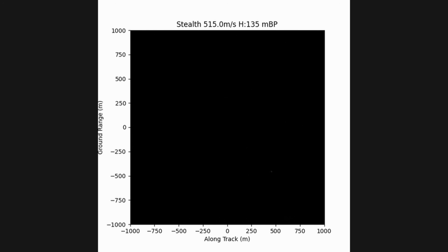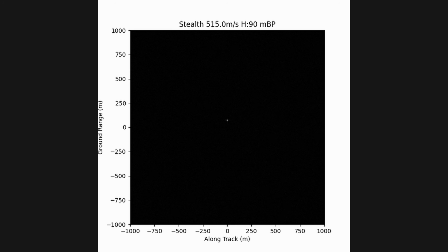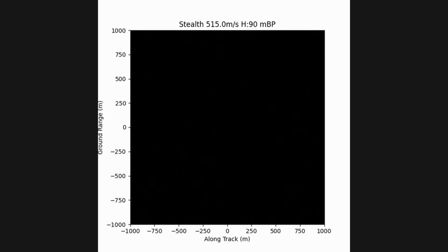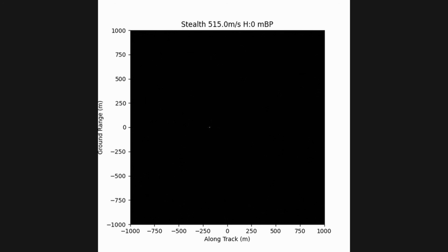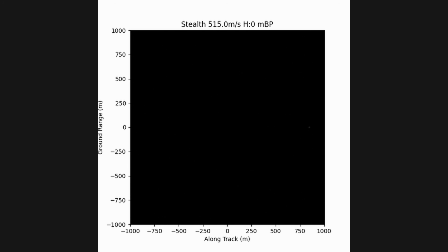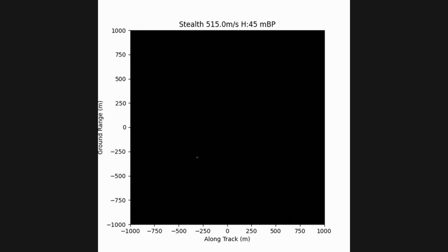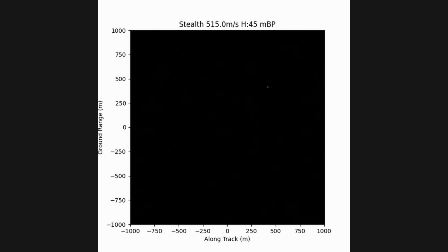In my simulation here, you can faintly see the stealth fighter, and this may be somewhat unrealistic because the radar cross-section of the point targets would be spread out over the whole aircraft and would be much darker than the clutter underneath. To track these, you'd probably need to either track the shadow, which would be the same shadow as the ordinary fighter jet, or use some form of clutter suppression. This can be done simply by subtracting the clutter that is stable between frames, or with variations of space-time adaptive processing that we will discuss later in this video.